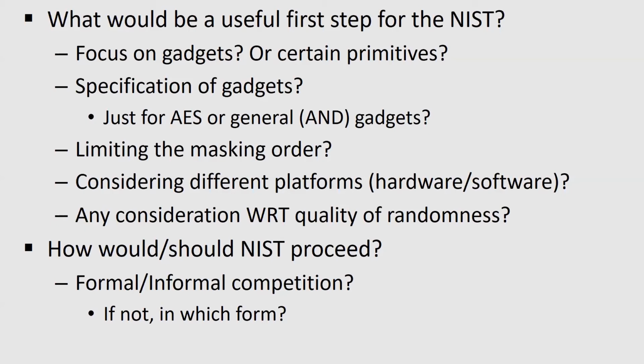It directly affects the latency of the circuit, because after replacing every gate with a masked gadget, you have a higher latency. You need registers, and then you instantly increase the number of clock cycles by a factor of, let's say, 10 or even 20, right? So should we consider larger gadgets, but still stay general? Can we use these larger gadgets for other implementations? If we are far from the AES now, consider the other NIST lightweight primitives.